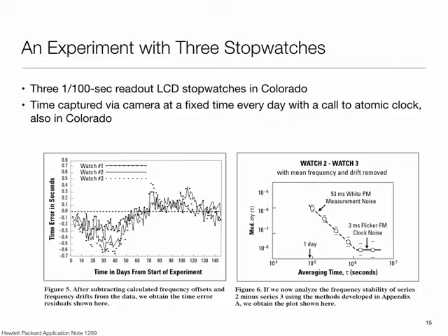So they basically say, I'm selling you a 10 megahertz crystal, but by the way, it can have a 10 part per million error, and you can calculate, therefore, what band the nominal frequency is going to lie in. Additionally, they would have some number specifying how this frequency changes over time. So they may say something like, over a band of minus 25 degrees Celsius to plus 50 degrees Celsius, how much would the frequency change by? That would be the other number, in the form of how much frequency changes for a given amount of temperature.